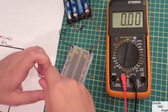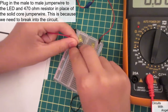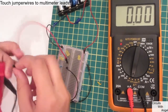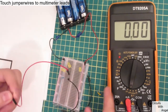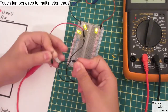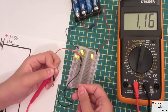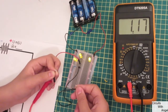Okay, now I gotta make sure that you know that the jumper wires are supposed to connect to the components, or else this won't work. So if it isn't working, make sure that things are connected. Alright, now we touch our leads to the jumper wires. If your reading turns out negative on your multimeter, switch your leads around and connect them again. It should work properly now. I thought I'd say that because I was a bit confused when that happened at first too.